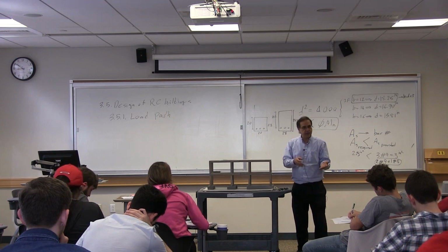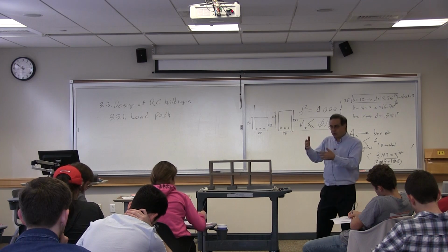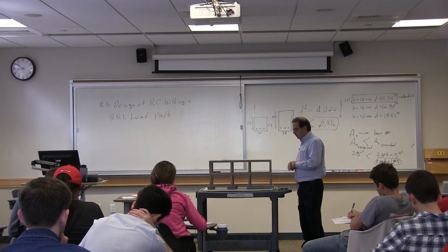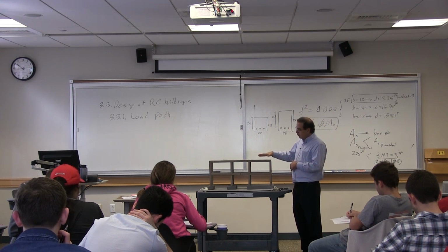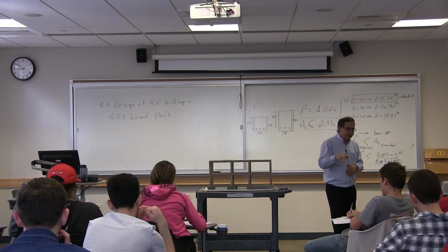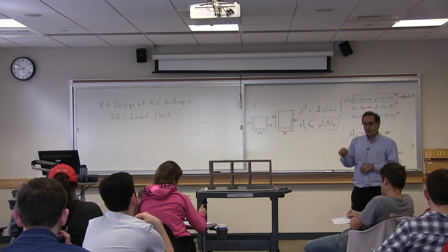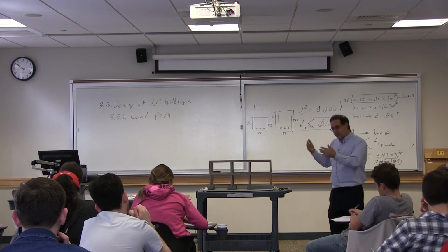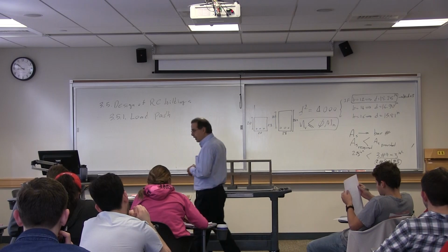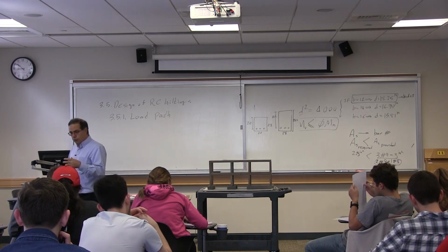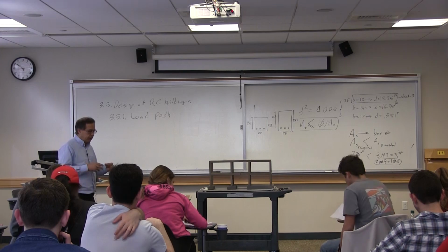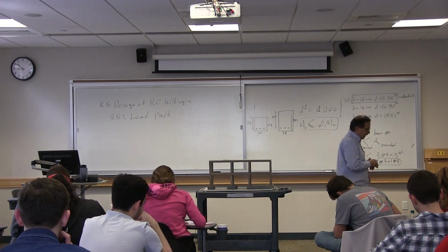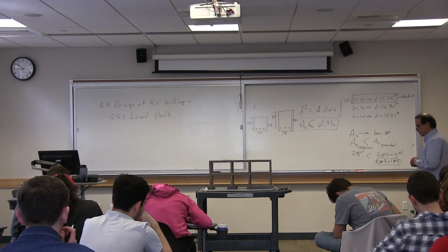There are buildings which have walls. That's what we are not discussing in this class. Walls are usually meant for lateral loads. Here we are focusing on gravity loads. When we design those elements, we will primarily design for flexure. Flexure would be most of the calculation, the more important part of the calculation, and the part that would control the design. We do the flexural design, and then we do other types of designs.